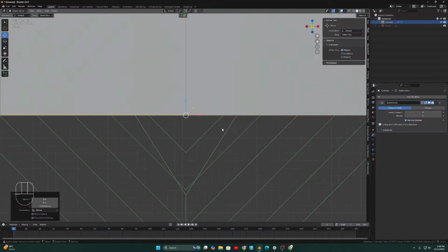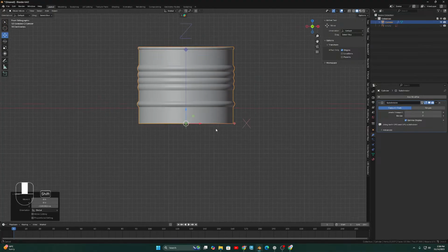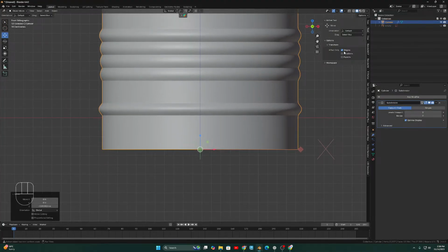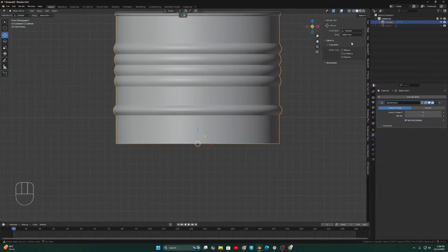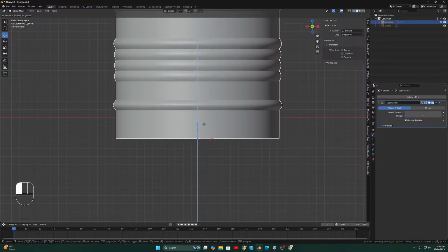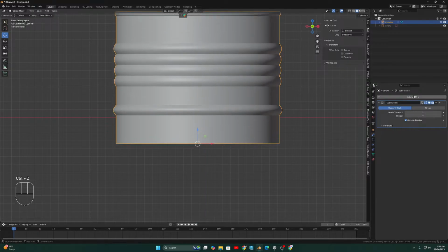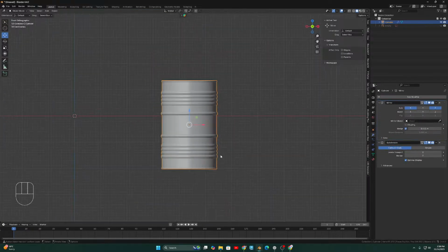Once your pivot position is set, you just disable this again. Now your pivot is here. Once this is disabled, if you are moving it by your pivot, your object will move. Now add mirror. It is pretty much simple. Done.